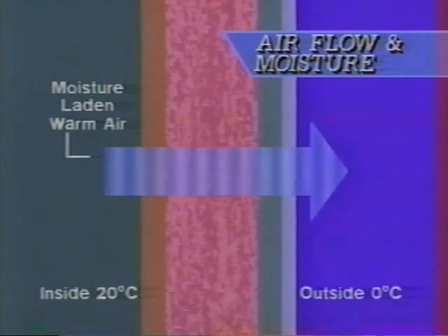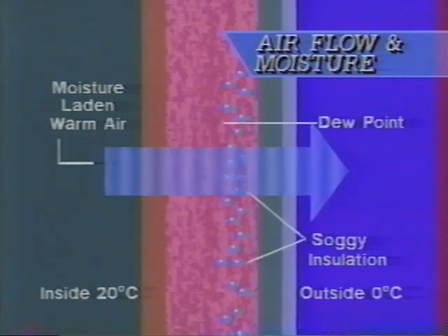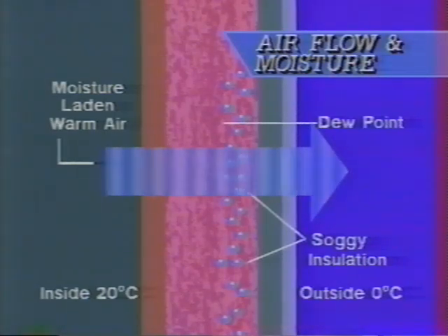Precisely. Also in kitchen windows very frequently and a number of other places. Nice basic science lesson. What's it got to do with building houses? Well, to stop condensation, we have to stop water vapor from getting into a location where it will cool. We need to keep the vapor out of the walls.